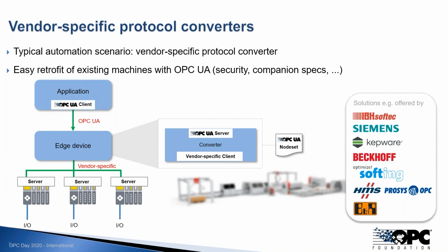Again, the OPC UA server is then able to connect to this server, and then it doesn't even see the difference between an old-fashioned machine which is retrofitted, a modern machine which is also compliant to this node set file, or another vendor's machine which is also retrofitted. All these are then in a uniform way accessible via the OPC UA server if it's compliant to the node set.